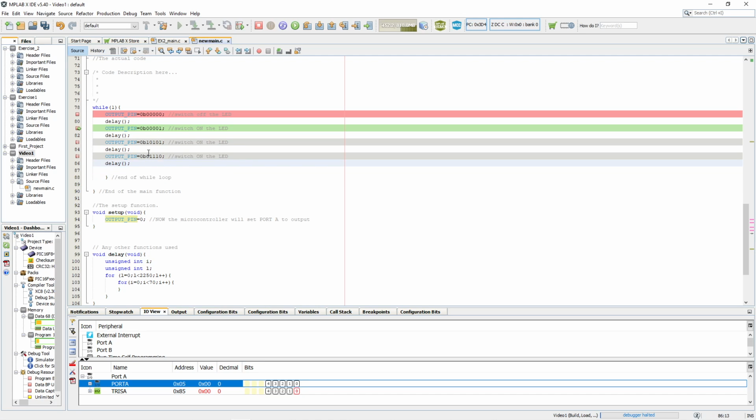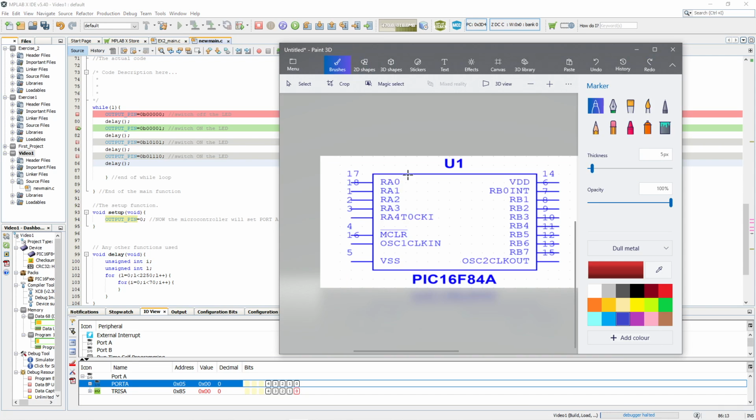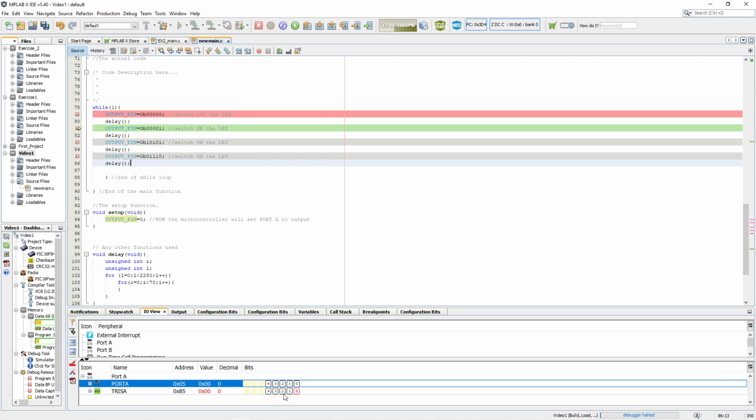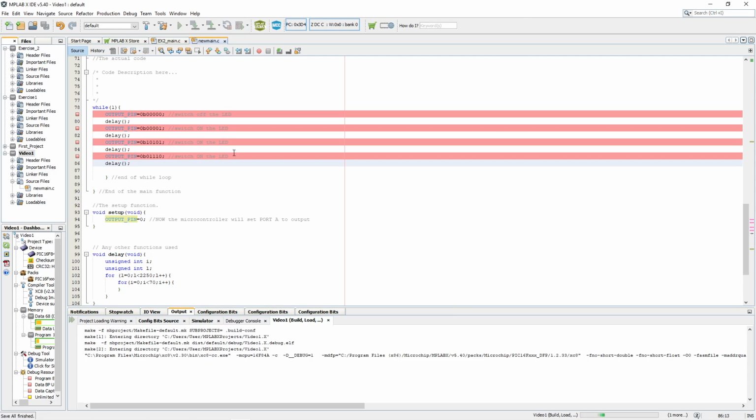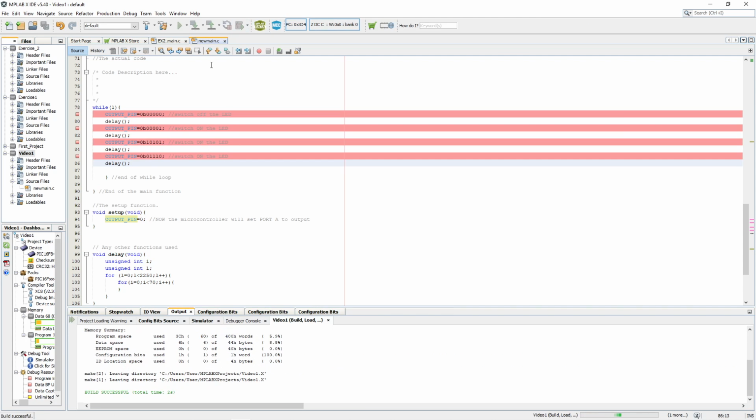So you can set the high and low values a lot faster than with Arduino, to be fair, but it takes a lot more time to set up. By using the trace value instead of the unique separate pins, because this entire port section has the same name, we can easily control them. If I forgot to pause it, there you go. I need to stop the simulation, then build it again to actually make the changes.